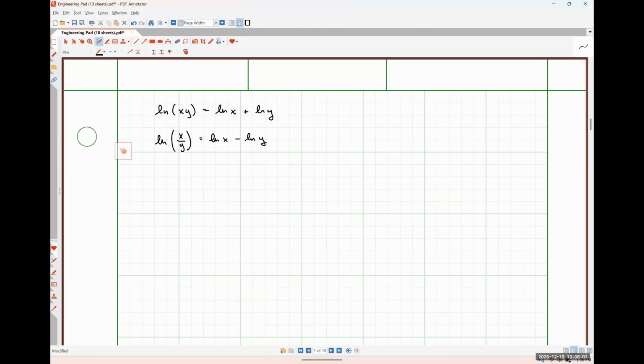So I'm going to introduce you guys to two circuits, one of which is called a logarithmic amplifier that allows us to take the natural log of a signal, and the other one is the anti-logarithmic amplifier, which lets us do the anti-log or the exponential, right?